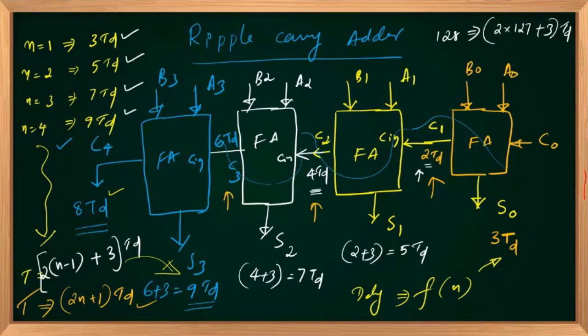So in carry look ahead adder, we will produce a logic expression based on inputs, so that along with the inputs, first carry output as well as second carry output, third carry output, etc., nth carry output, all are implemented using logic gates simultaneously, right? We should not wait for carry out from the previous stage.